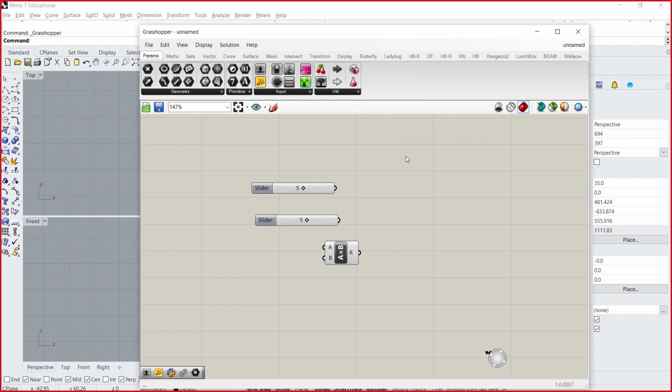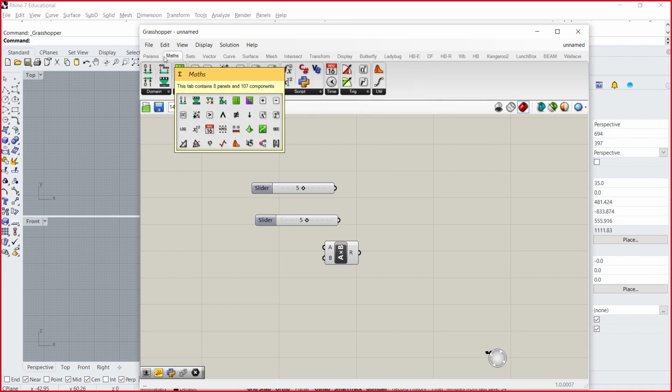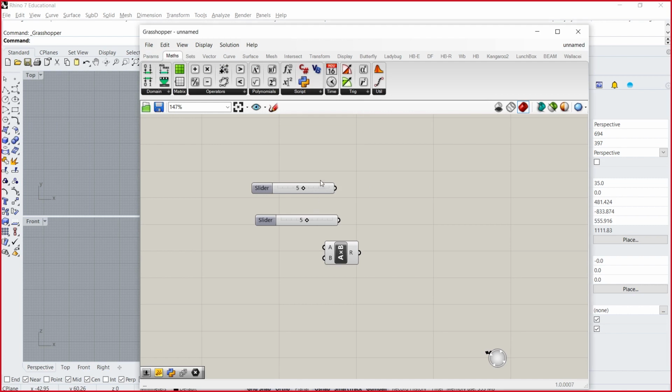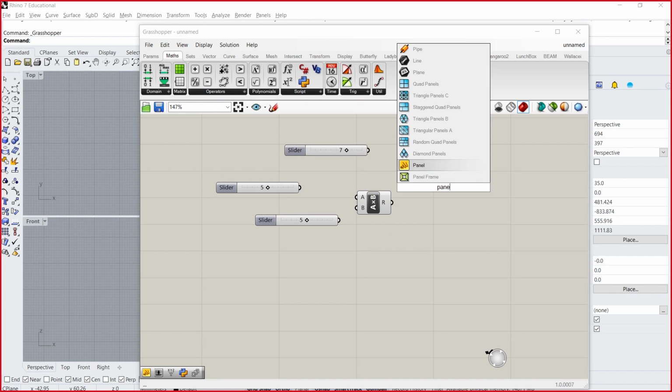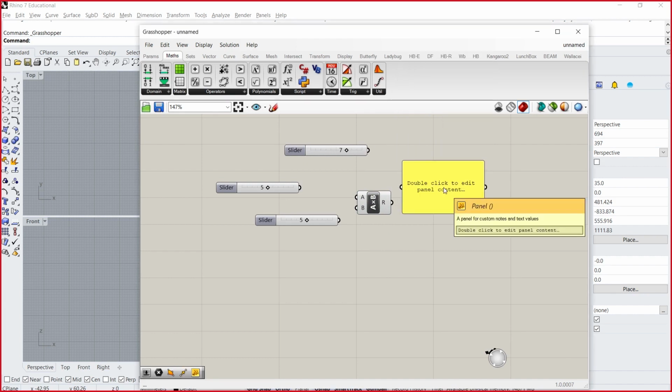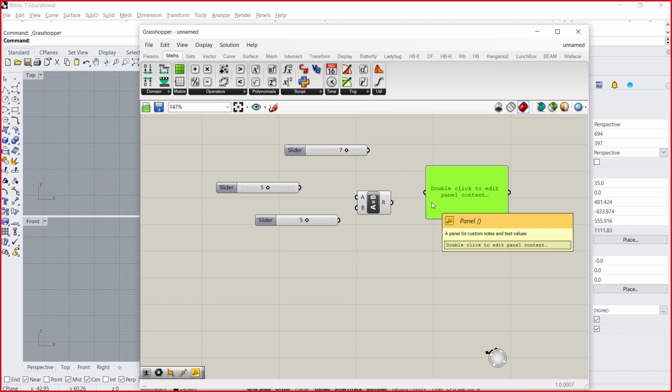Yeah, so here, double click, you'll get a prompt. And then you just type in multiplication, okay? So if I double click and type number 5, I get what's called a slider, right? So it's a form of input. A slider is basically a number that I can change based on a range, okay? I want you to double click again and type in panel.